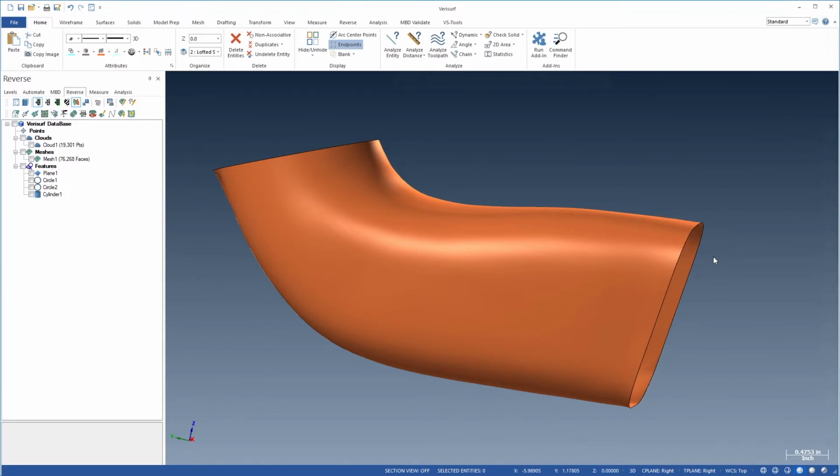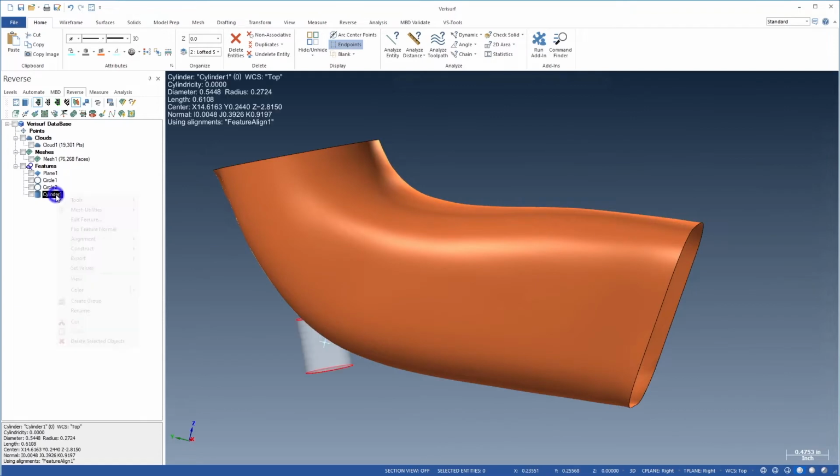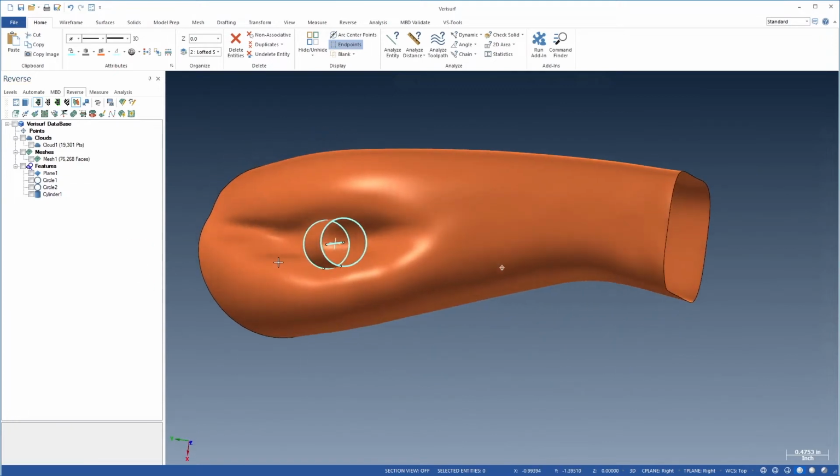Let's start by creating a CAD surface from the measured cylinder, which defines the valve guide through hole. This can be measured anytime after the Master3DGage is aligned to the cylinder head. We'll right-click Cylinder 1 and choose Export to CAD. We'll then clear the highlight and view the cylinder.